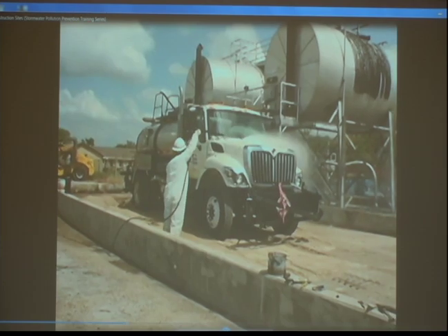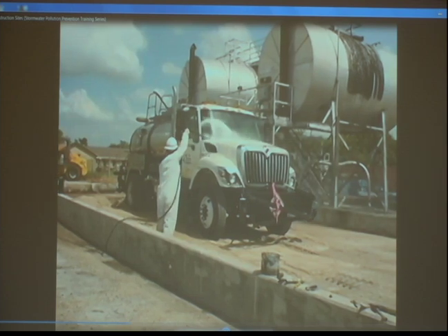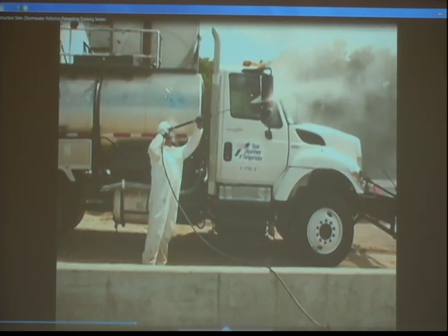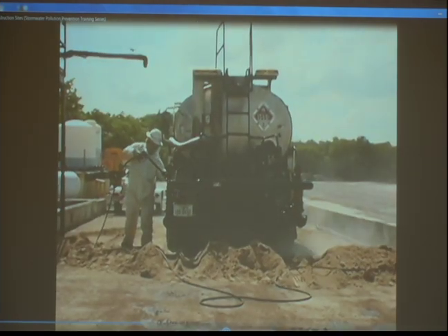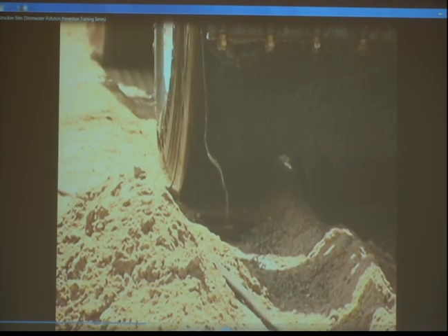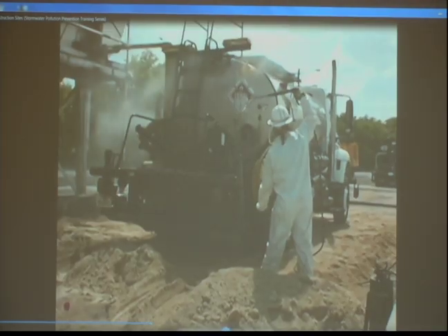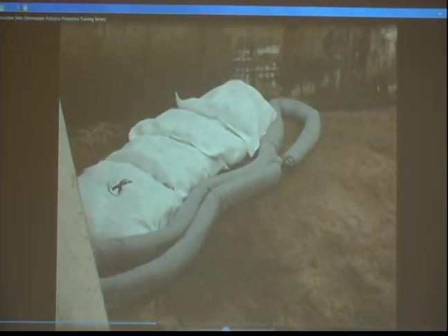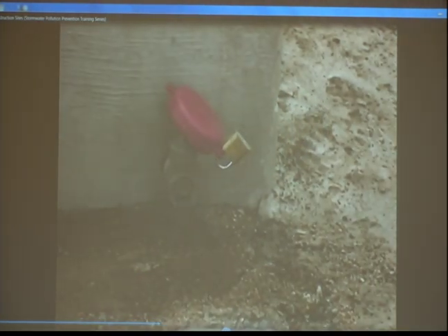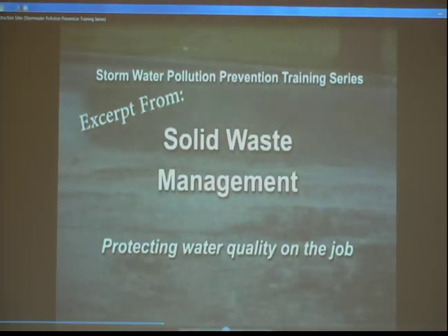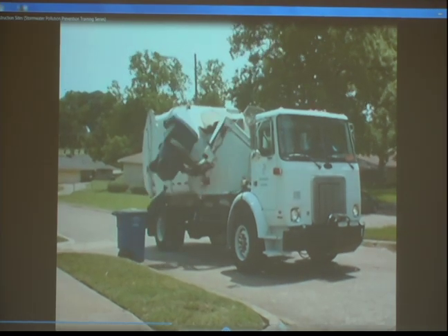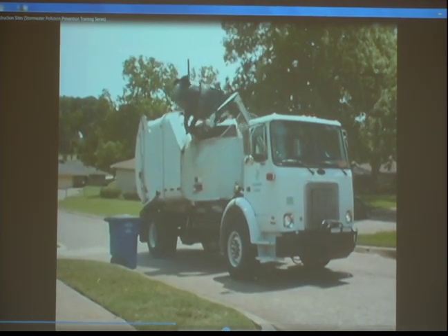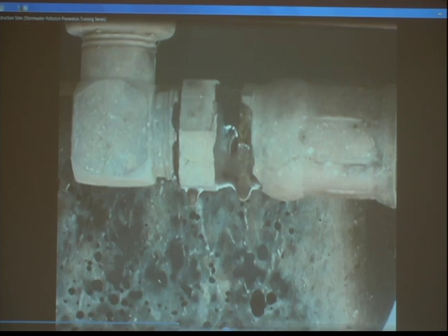Clean trucks, equipment, and tools in designated equipment wash facilities where wash water will be contained. If no wash facility is available, clean equipment over a layer of absorbent material spread on a paved surface or heavy plastic sheeting. Sweep up the absorbent and dispose of it in accordance with state and federal regulations. Make certain that hopper drain plugs are always sealed during collection. Check vehicles frequently for leaking fluids and notify a supervisor of significant leaks.